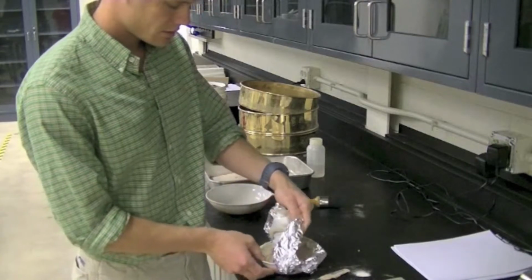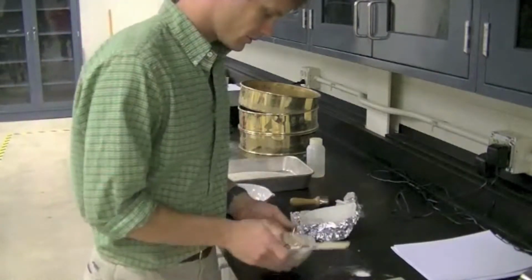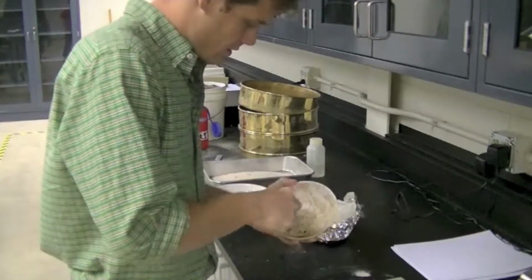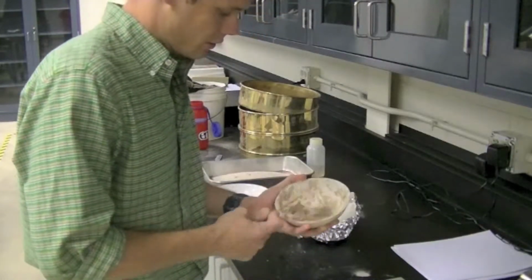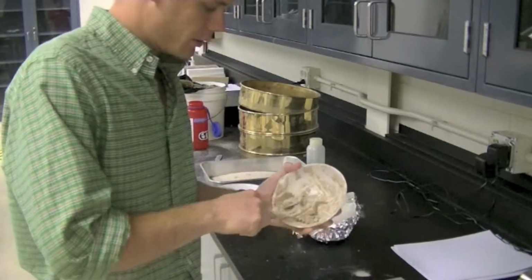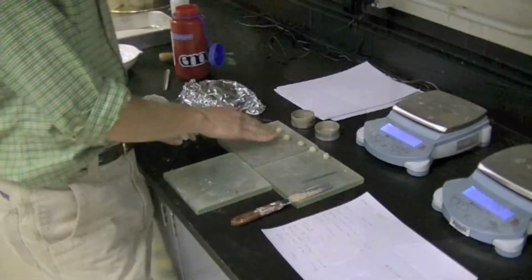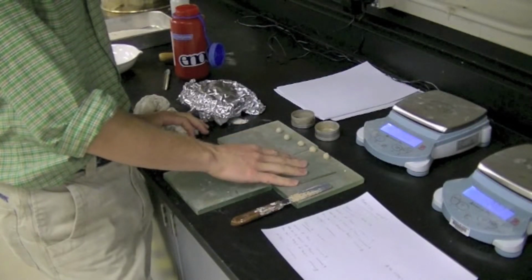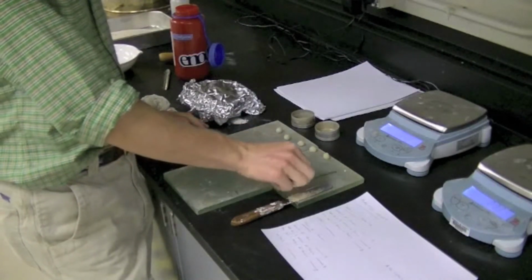After 16 hours of soaking, the plastic limit test is ready to begin. Uncover the soil sample, remix the soaked soil to ensure consistency. Re-roll the soil into 1 to 2 gram balls. Make 5 of these balls.